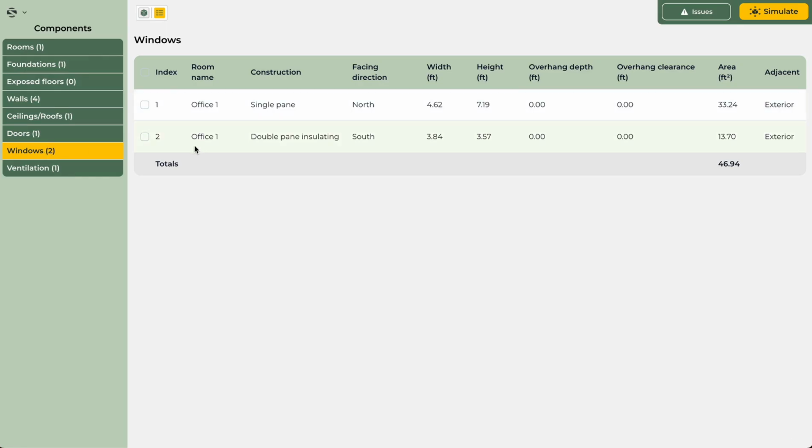So keep in mind that what you see in table view are the things that are going inside your energy simulation. And those are the surfaces that have a temperature gradient on their 2 sides. If some surface is marked as interior, that means that surface is adiabatic and it's not going to have an impact on the model, and therefore we don't show it in this table view.